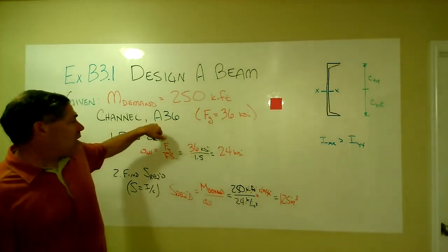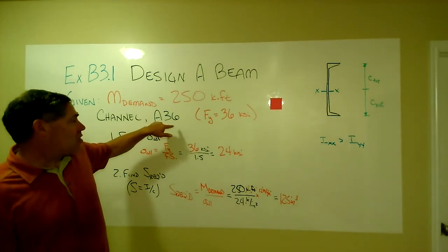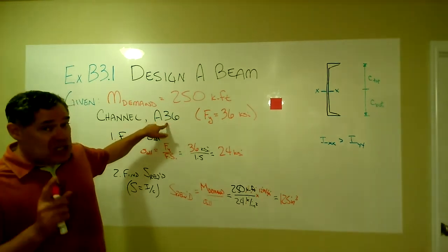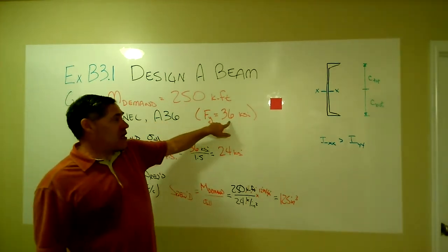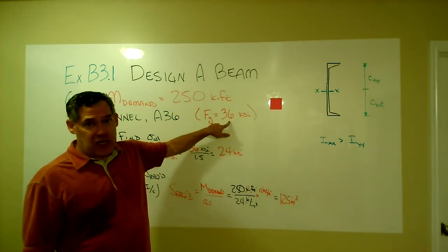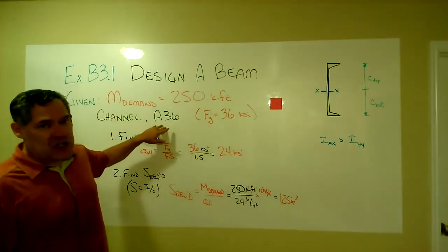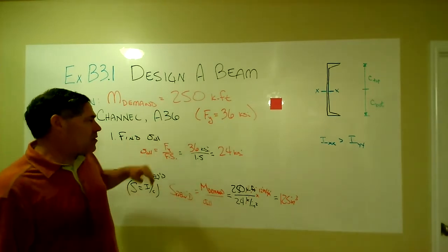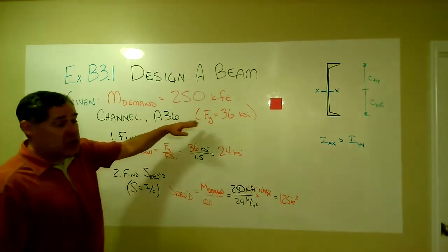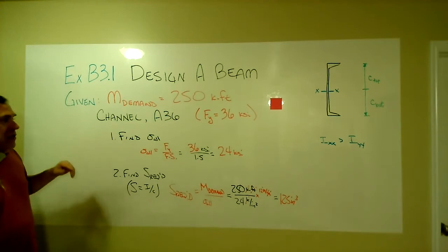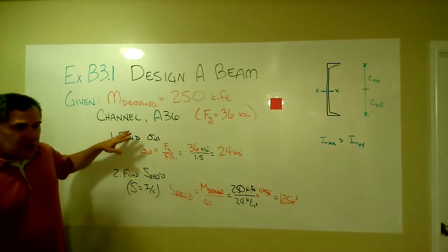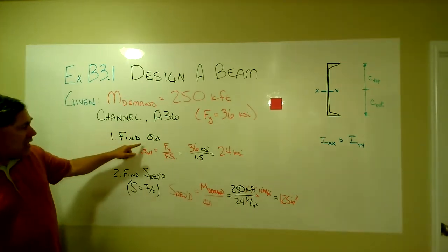And it turns out with the ASTM designation A36, this number 36, just for this series happens to coincide with the yield stress 36 KSI. That's where it came from, but that's not generally the case. It just happens to be in this particular one. So you don't actually have to look it up. You just have to remember A36. Hey, that's 36 KSI.